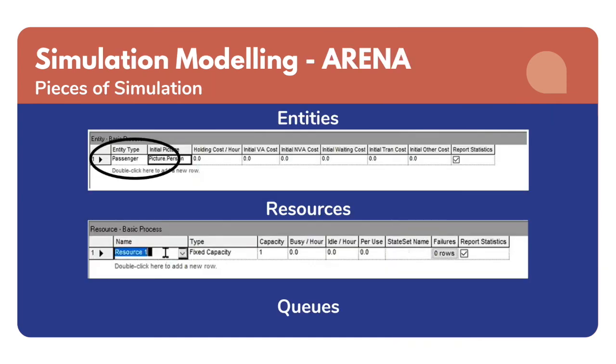These pieces are the key players and data which the process will use when the model starts running. Entities are considered the players of the model, and they are the evacuees in this study. Resources are the hallways being utilized by the evacuees. Take note that the simulation starts when the evacuees enter the system, or leave their rooms for that matter. Therefore, they are already located on the first floor and/or the basement hallway. With this, we considered using only one quantity of hallway as a resource.